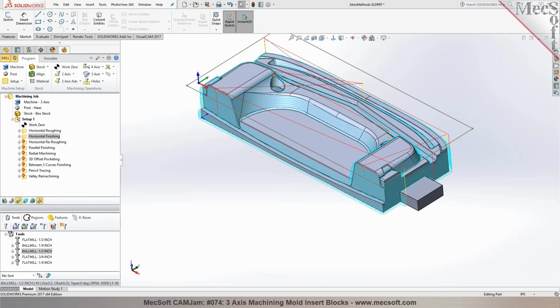Yeah, we do not have any specific library of clamps in the CAM programming part of it, so you probably have to look at whether SOLIDWORKS has a toolbox where you can find those, or you may have to build something in there and you can use it on other parts. So, we treat everything you see here as basically the part. So it's not going to cut whatever is inside this, because the cutter will not gouge into those areas. You know what I mean? Yeah.